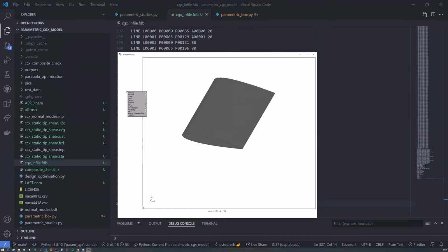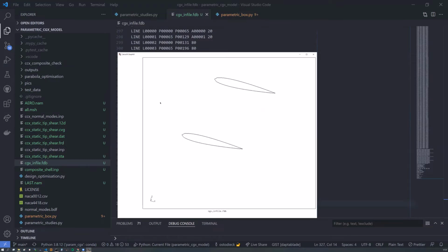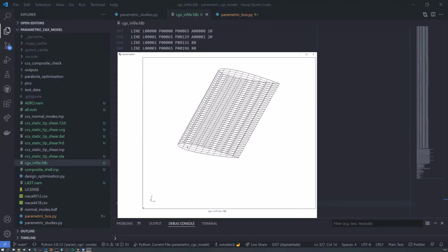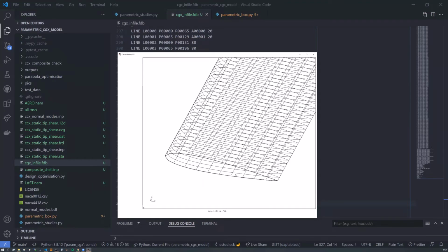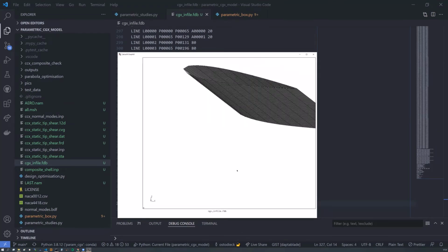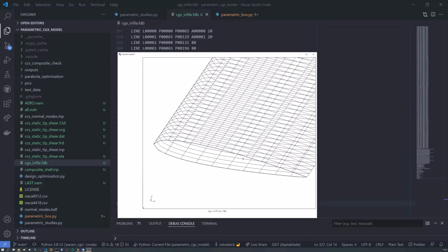But if it's difficult to see this, if you toggle the culling back front, now you can see much clearer that if this is appearing as transparent, this is actually the top surface of the shells, and the bottom surface is this dark gray. And if you want to see the mesh, we can switch that on. Element edges, there you go. So you can see that we've got the same sort of mesh that we had before.